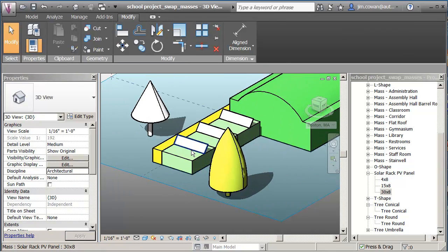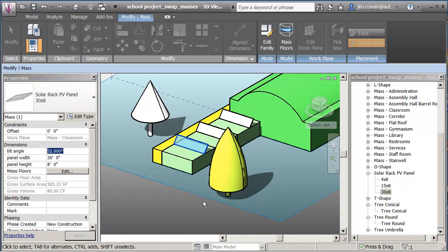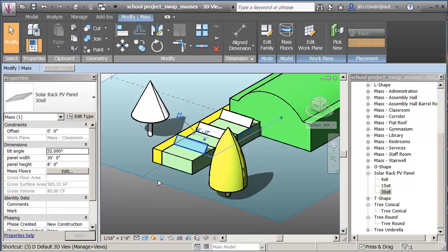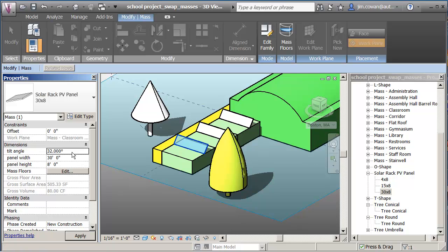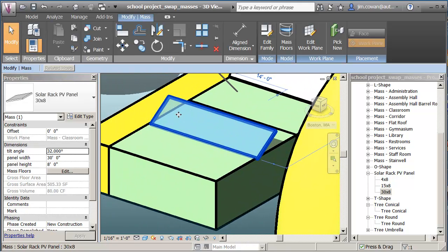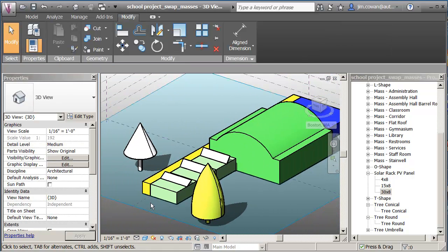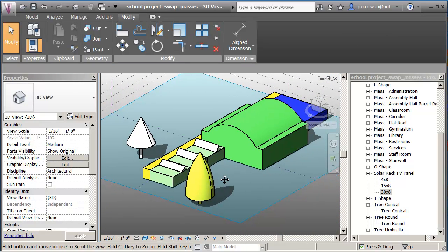And similarly, if I pick on the PV rack here, I could tell it, what if the angle needed to be less pronounced. So matching it maybe with the latitude of the site itself. I could adjust the slope to get the angle that I want. So all of that can be parametric, giving you families that you can assemble, but also you can control to modify the size.